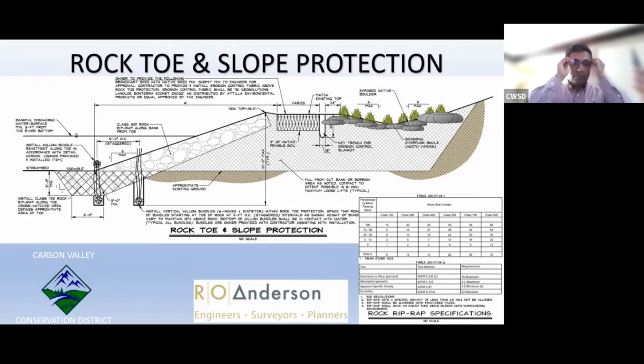So as you can see, the riprap, in certain sections we have about 10 to 12 feet high, right? We can't really go that high with the riprap because of the funding limitations, and no one wants to see all riprap on the banks. So we stay about 3 to 4 feet, basically just above the bank for discharge elevations. And like I said, this is the trench that I was talking about. We found it very important to dig down at least 3 to 5 feet, so we don't lose the work that we did.